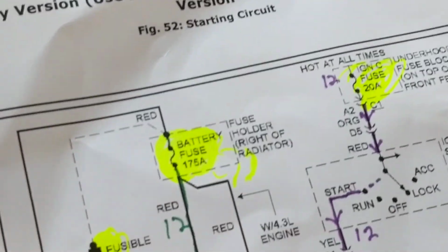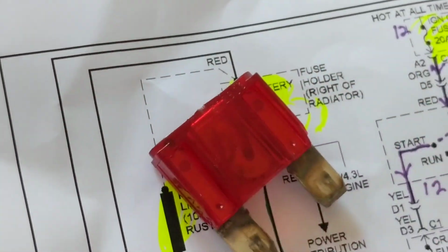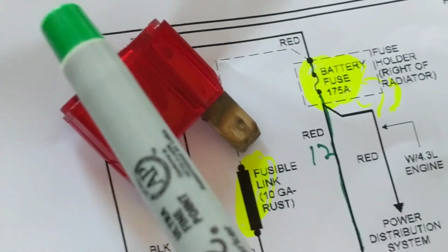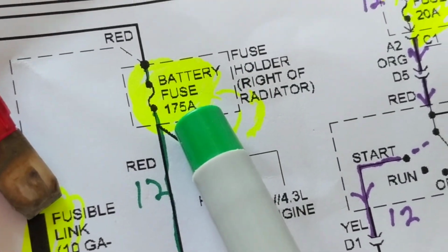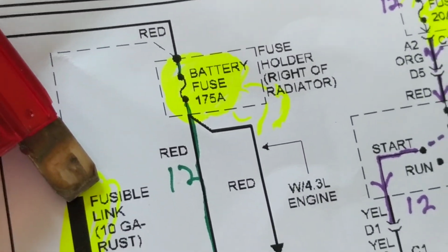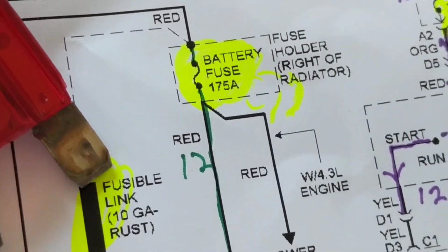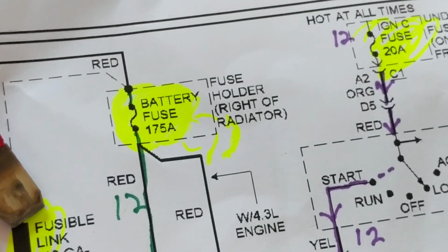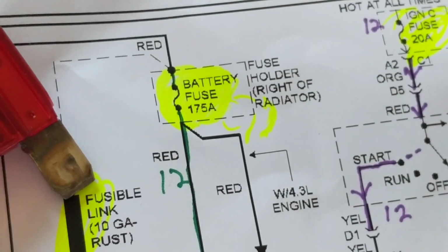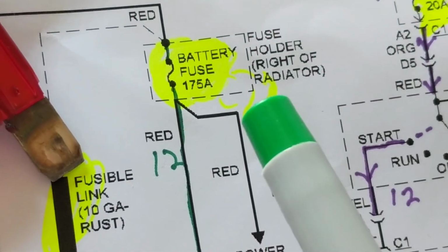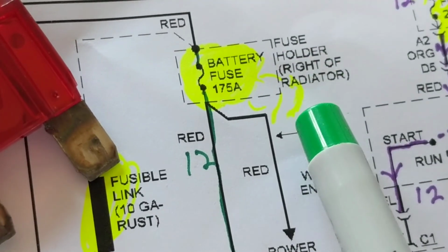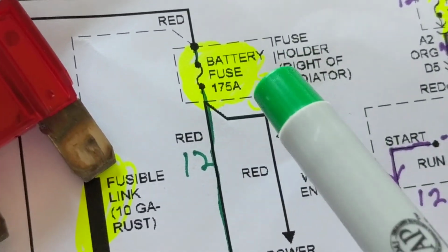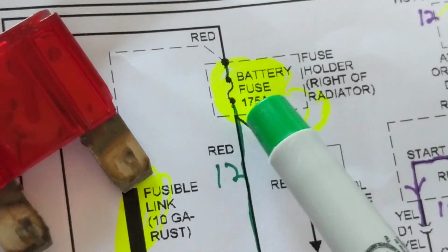Now, the fuse. There are many types of fuses. There are maxi, there are mini. This being a maxi, it does not say that on the schematic. What it does say is the location of it for automotive, but otherwise you will not have even the location on, let's say, audio or video. If you're troubleshooting microprocessors, it will not tell you the location. This is automotive, so it tells you the location, which is a good thing. It tells you the rating, 175 amps. It will not tell you the color. Every color is color coded.